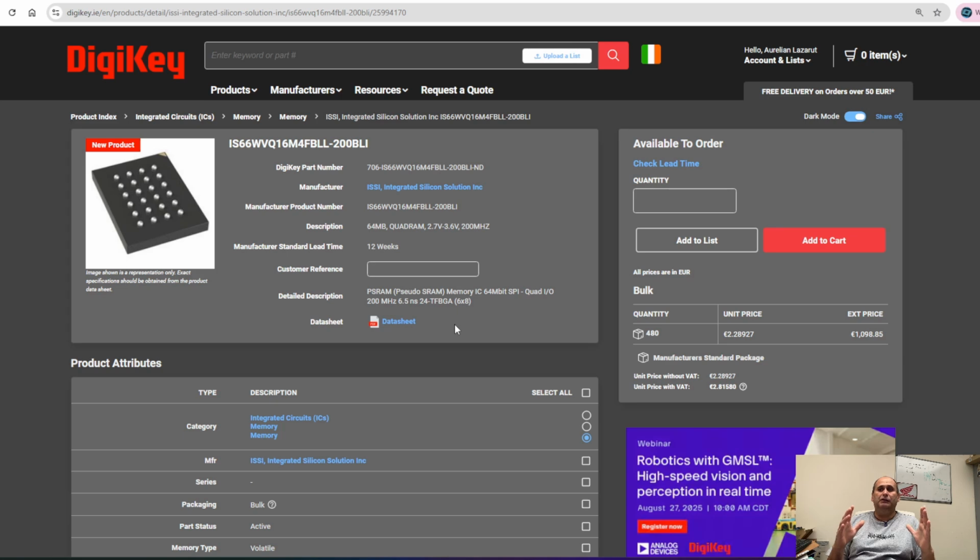Let's assume that your system reads continuously that memory, scans that memory. That's the use case, for example, for a display controller. A display controller reads the memory, the frame buffer, the content of the video memory continuously. From the first line, it just goes and reads through. In that case, you don't need refresh cycles. Why don't you need them? Because you're going to access everything linearly anyway, so that is going to refresh the memory.